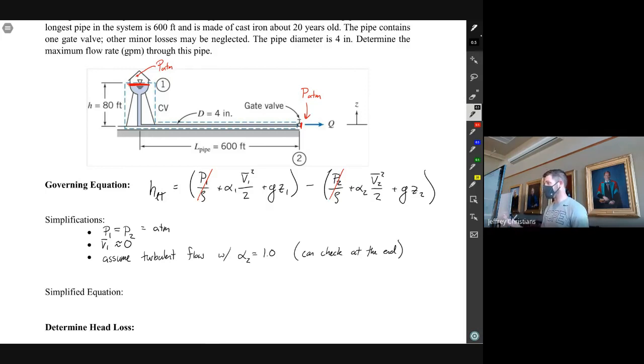If you had something that was specifically pressurizing that, if you don't have it open to the atmosphere, as the water level drops, you'll actually form a vacuum there, which will decrease your flow rate. So it's easiest to have a vent there so that as the water level drops, air is going to come in and refill it. So it'll probably be atmospheric.